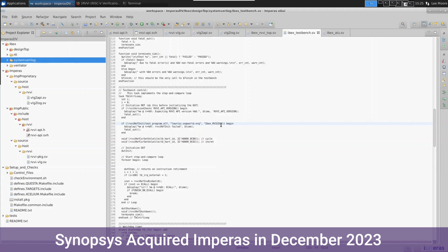Interestingly, there are a number of other parameters that can be set at runtime as well, and I'll go through some of that. And you can use this to layer on top additional capabilities that are available but switched at runtime. So we've worked with many groups that developed RTL, and an example of this would be the OpenHW Group, and they have some switches that configure the RTL, such as including or excluding the PULP instruction set. And so what you can do is you can configure this at runtime as well for the reference model that's being used for the comparison.